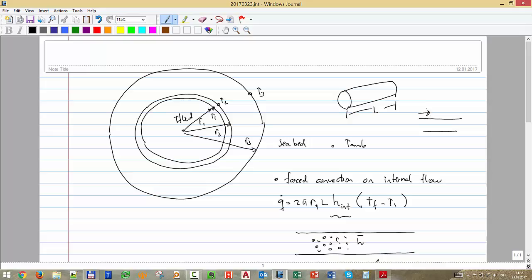And you have another type where the fluid is not moving, is stagnating, but due to the heating of the fluid, for example in the case of water, some particles close to the wall are going to become hot, their density is going to reduce, and then they're going to go up, and the heavy molecules are going to go down in contact. So you have some kind of circulation, but it's a product of the heat transfer. That's what we call free convection.